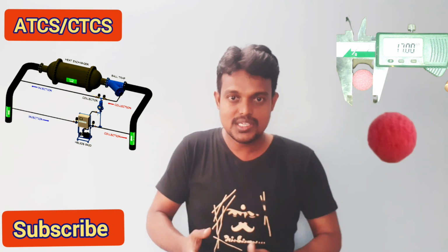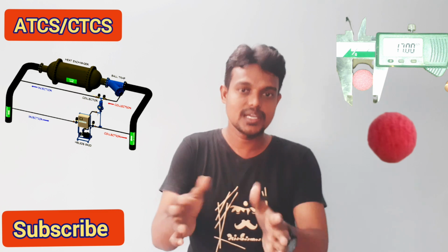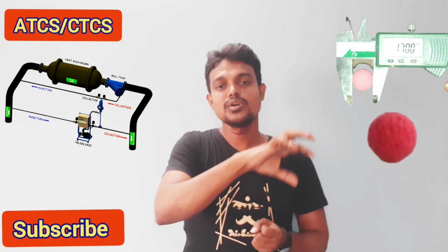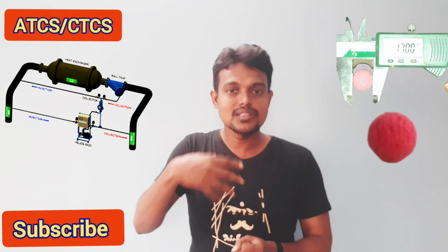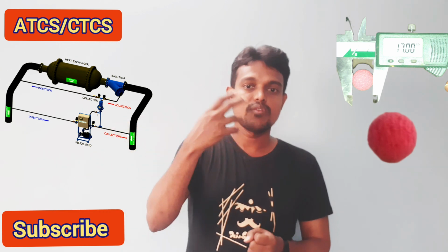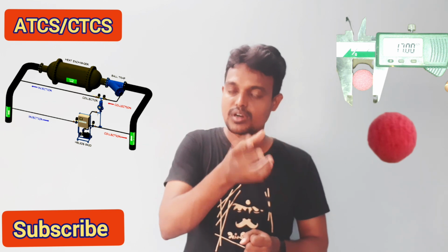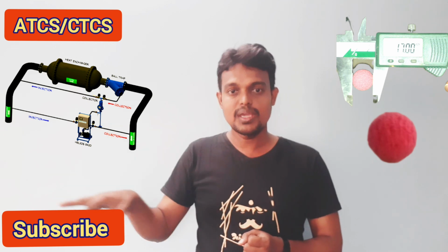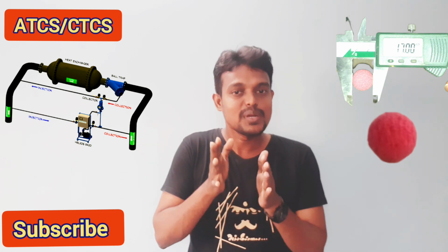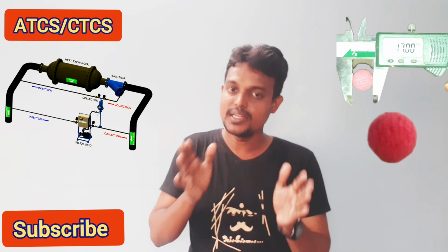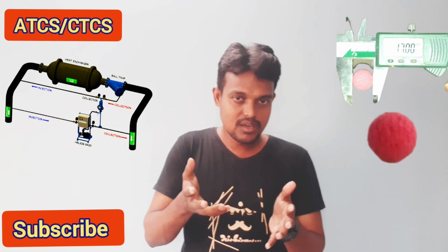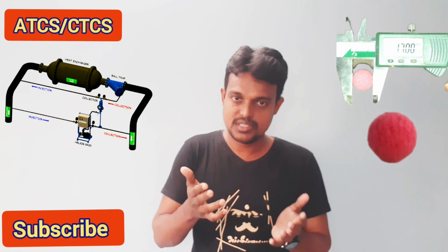What I told, right? Initially we will be injecting balls inside the condenser coil. After that we will be sucking the balls from the ball trap. Based on this process, your actuator will open. The water from the pipeline will also be coming and going into the system. So this is the principle of your auto tube cleaning system. I already conveyed what the advantages of the system are.